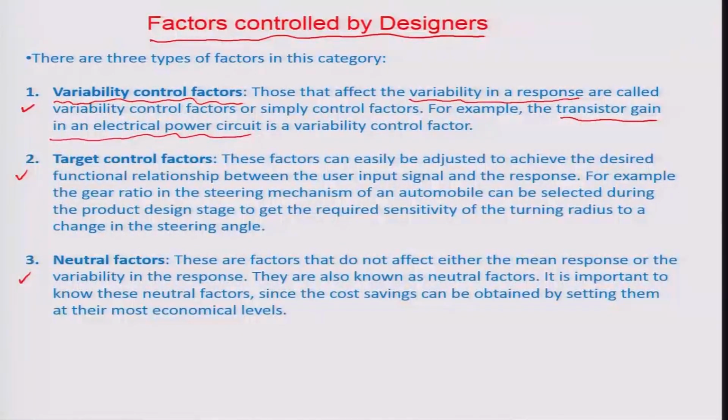One would be much more varied than the other, and it may be appropriate to go at a higher level of output voltage and put a resistance in series, so that there is a drop in voltage and the available voltage comes down to the desired level for the system, and all you are ensuring is control in the variability aspect by doing this.